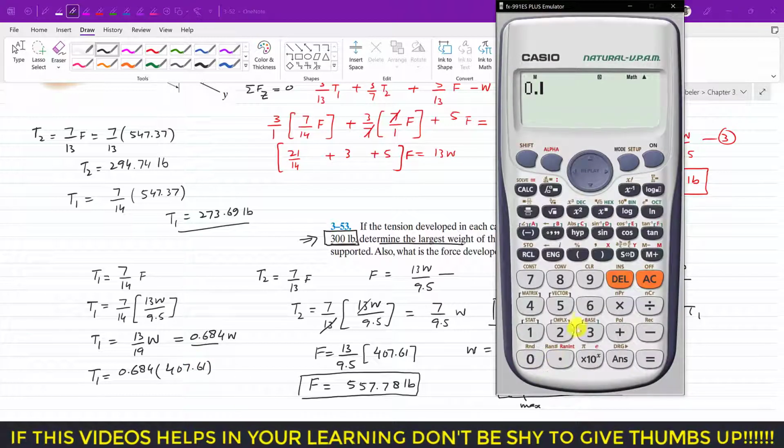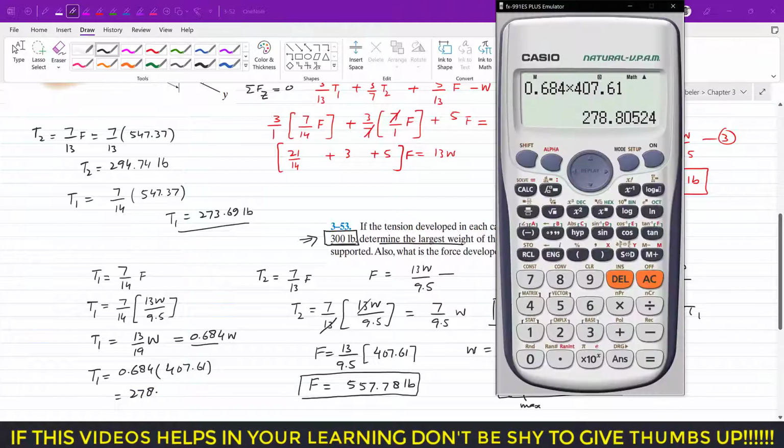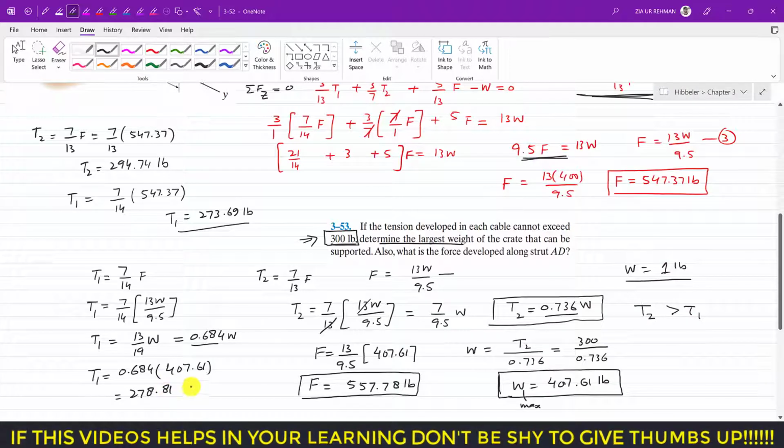So 0.684 multiplied by 407.61 is 278.81, which is less than 300 pounds, the maximum tension that it can support.